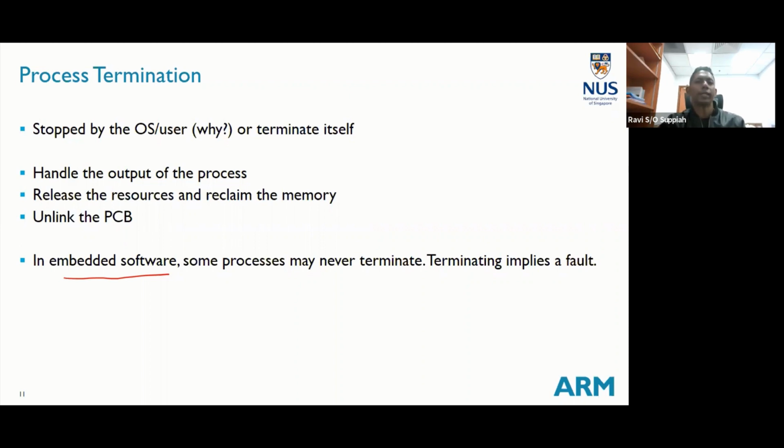The whole idea of creating tasks is you want to be able to do something either periodically or whenever some event happens, correct? So taking those scenarios into account, you create tasks for that. If it's just a one-off thing, like maybe when the system first boots up, you want to play some melody, some tune, and it's just a one-off thing, you don't need to create a task just for that. You can just create a function, and some startup task can call the function, and then that's it. Correct? So the idea of termination is more for general OS.